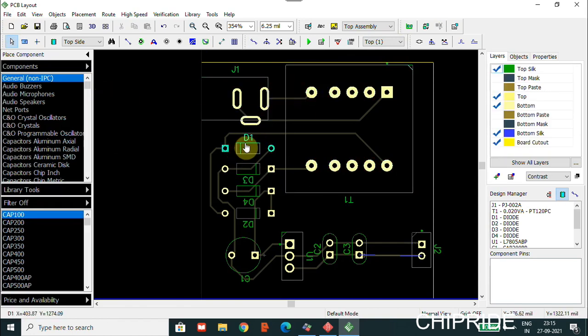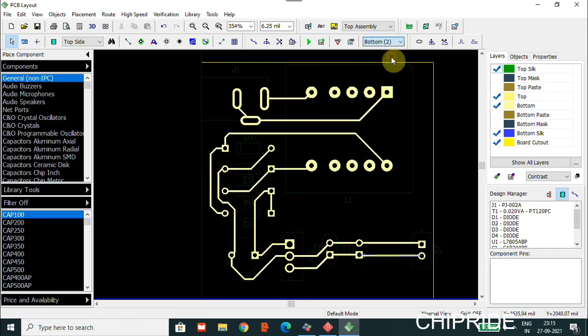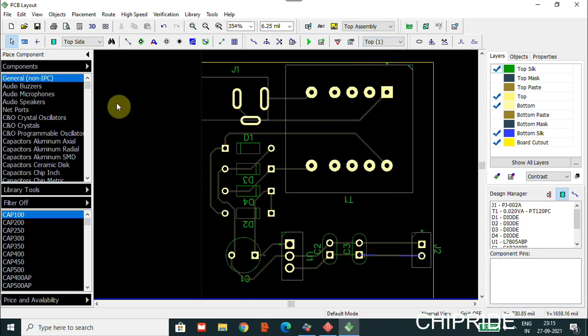So you can see, when we have followed the symmetry, where the components are lying, similar components are lying in a single pattern, and you can see the capacitors in the same line, and now connectors at the edges. So you should concentrate on these things, then the design at the bottom side. All these things have to be concentrated properly.